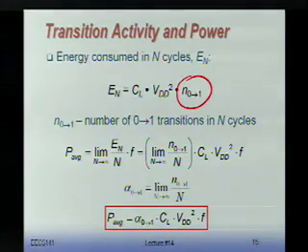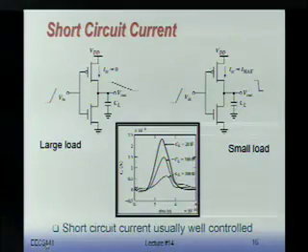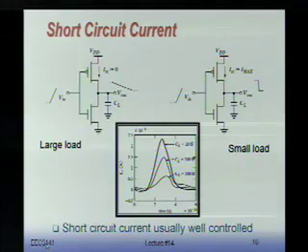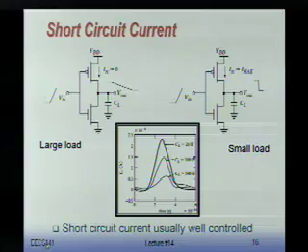Okay? So that's what I wanted to talk about. Dynamic power, fairly easy to find. By the way, if you run in SPICE or Spectre, you know how to find propagation delays, right? You look at the 50% point at the start, 50% point at the other waveform. You actually have some very simple commands in SPICE that allow you to do this automatically.